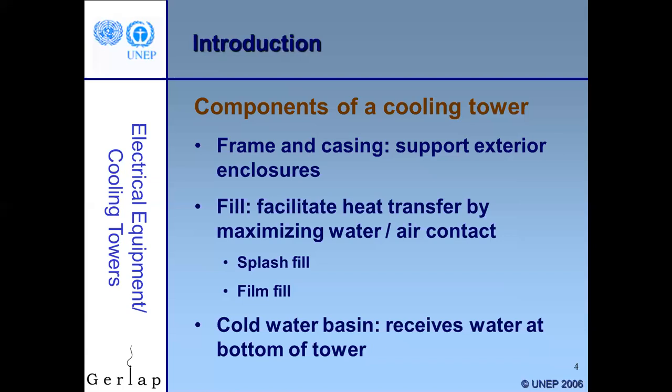And we talked again previously a little about the cold water basin. It's at the bottom of the tower. They oftentimes in colder climates will have heaters to make sure that we don't form ice and freeze this thing up in really cold weather. They're typically electric resistance heaters, which are fairly expensive to operate. It would be possible to use steam or hot water or some other heating source, but because of the fairly remote location of cooling towers, they are typically electric.